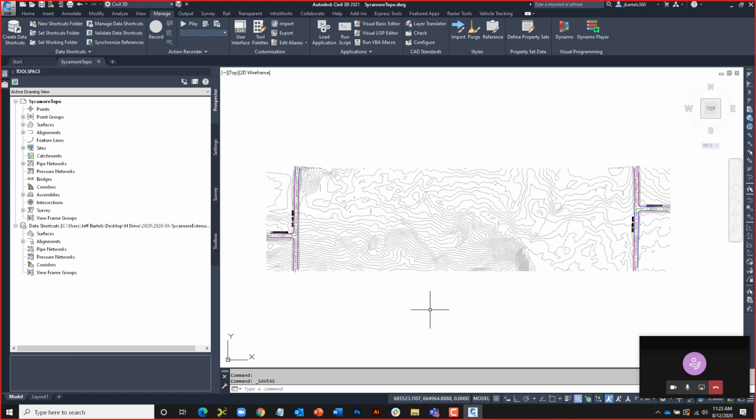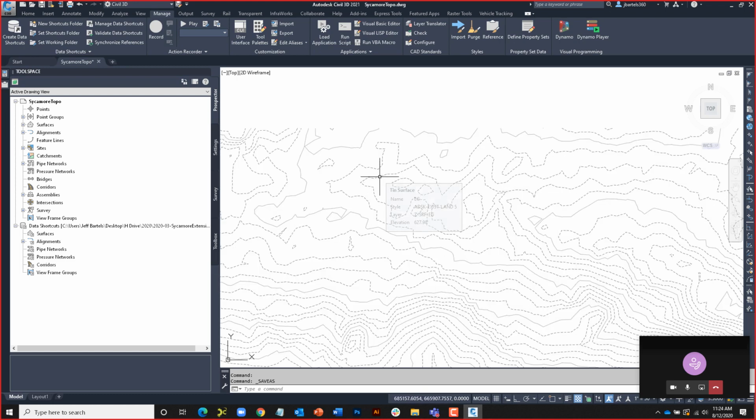If I was the surveyor and I captured this, I look and say, you know what, this drawing, I've created an existing ground topography here called EG. This would be helpful to other people associated with this roadway extension. Somebody may need this surface to daylight their corridor. Somebody may need this surface for earthwork calculations. So I am going to create a pointer or a shortcut so that my project is aware that if anybody wants this surface, they can find it in this drawing.